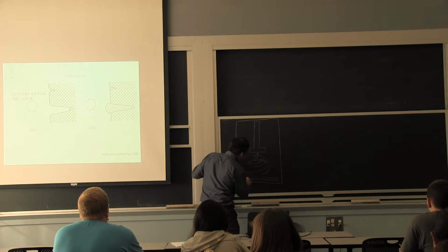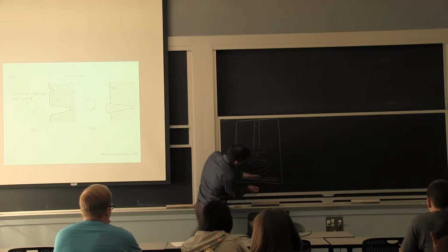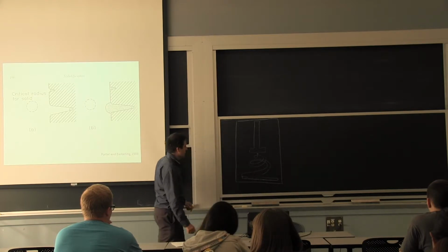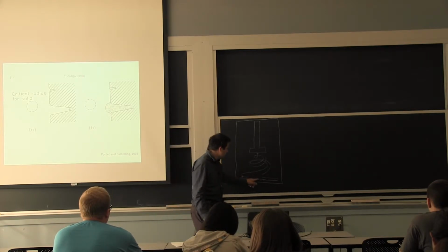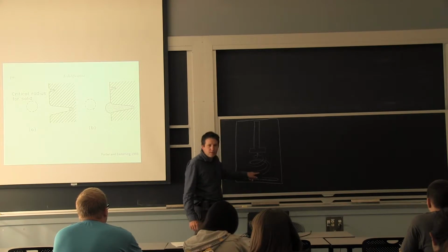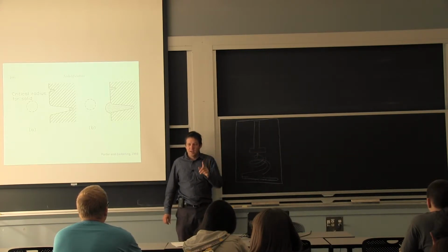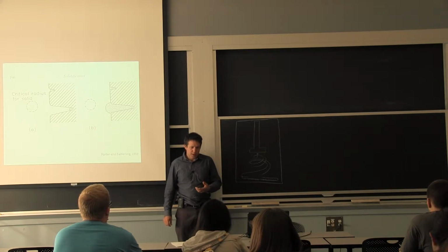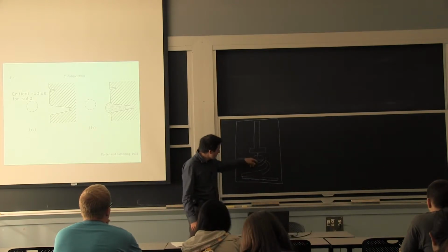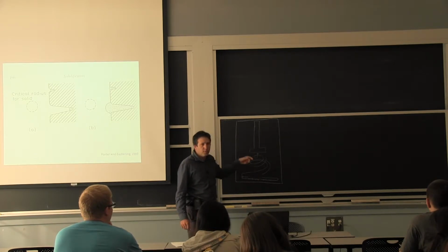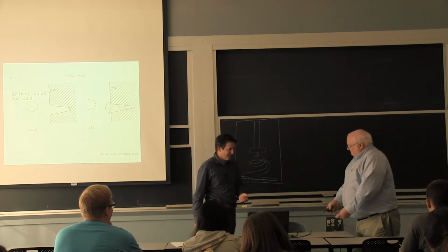I'm forming a bunch of crystals, and actually need a little more space here, but that's still fine. And the crystal that's going to go the faster is going to start engaging in that spiral. And by the time I'm done with the spiral, I only have one grain. The winner grain, which is the one that maximizes the heat extraction, so the thermal transfer, and it's also well oriented for stacking purposes. Yes?